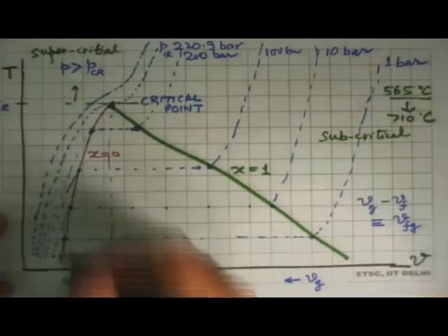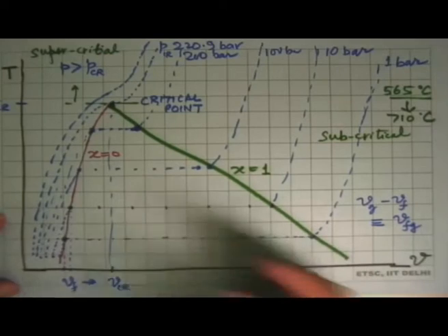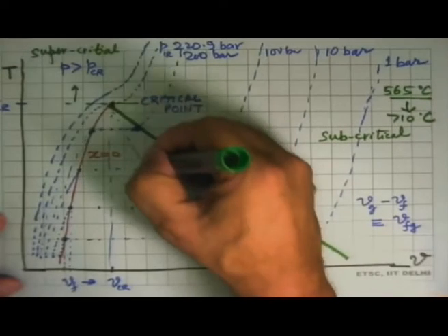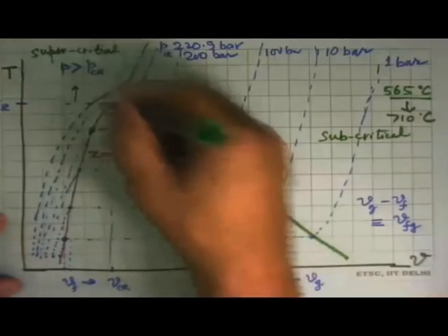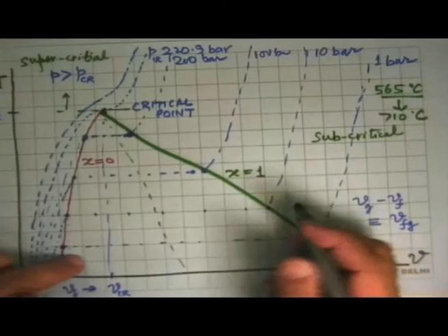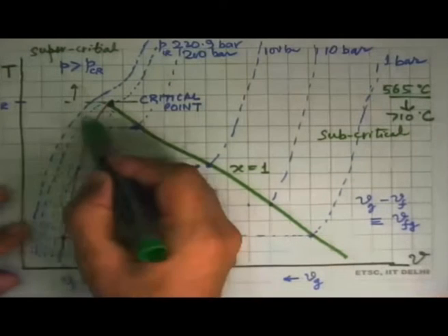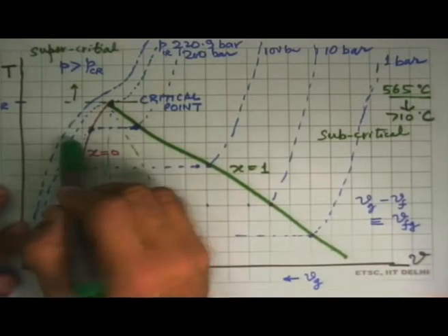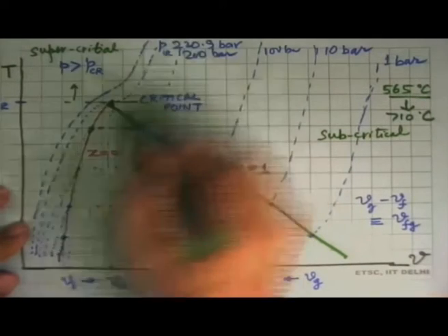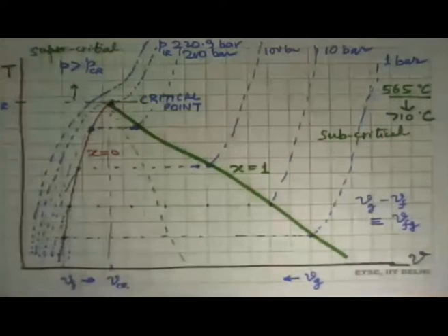Okay, so what it tells you is that as you go from left to right, x goes from 0 to 1. So in this, one can draw lines which are somewhat like this, and say, well, these are constant dryness fraction lines. X is equal to 0.6 is this much, x is equal to 0.7, x is equal to 0.3, they are like that. All the definitions that we had are valid for all this discussion. This is a saturated liquid. Left of this is a compressed liquid. This side is superheated vapor. In between, we define the dryness fraction. And the top, this is the critical point.